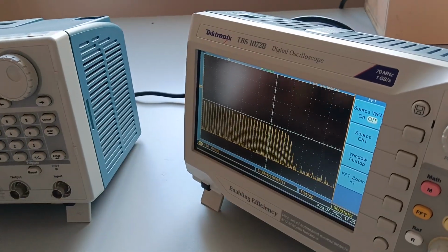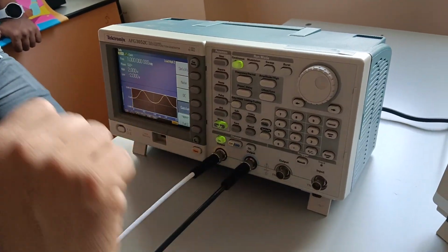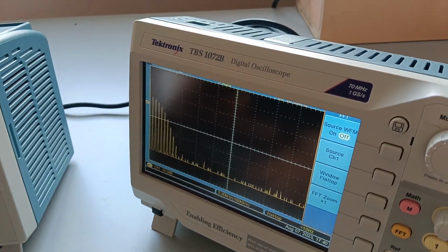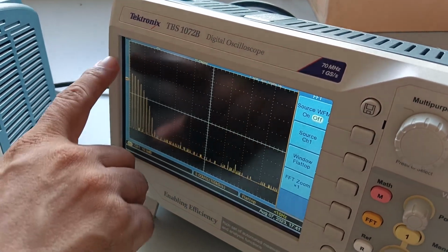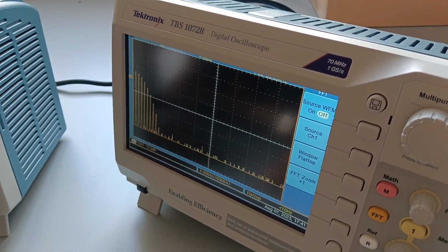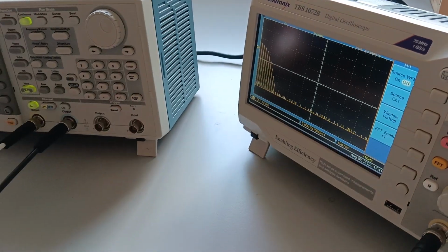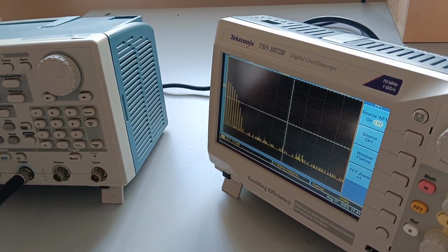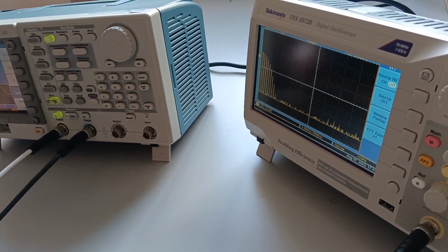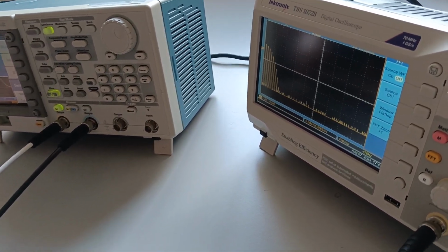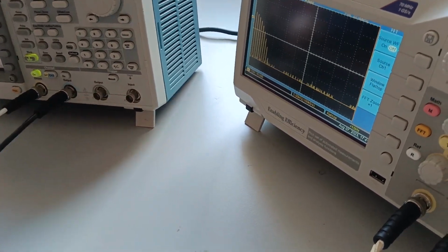Okay? The same thing let us do with Gaussian. What is the Fourier transform of a Gaussian? Gaussian. But this, look at this. This is not Gaussian, it is parabola. Because I told you this is log scale. Okay, so in frequency domain it is Gaussian, right? So because you have taken a log decibel, it is showing parabola.